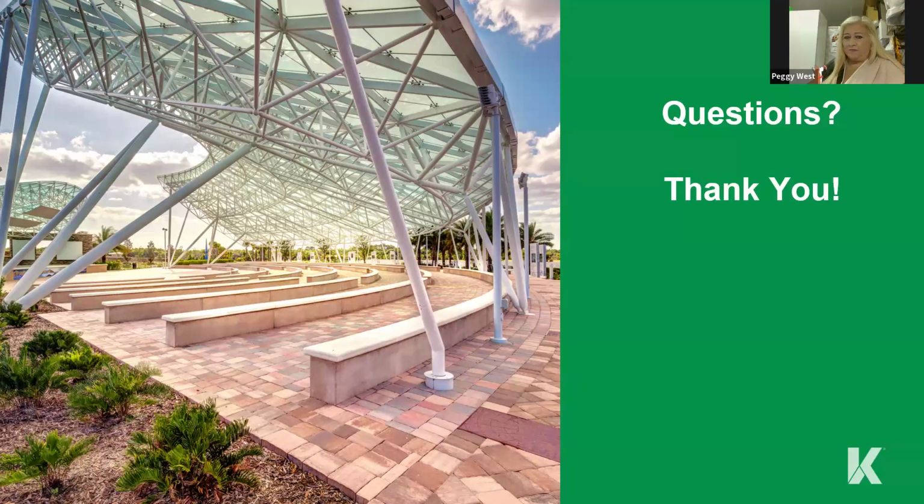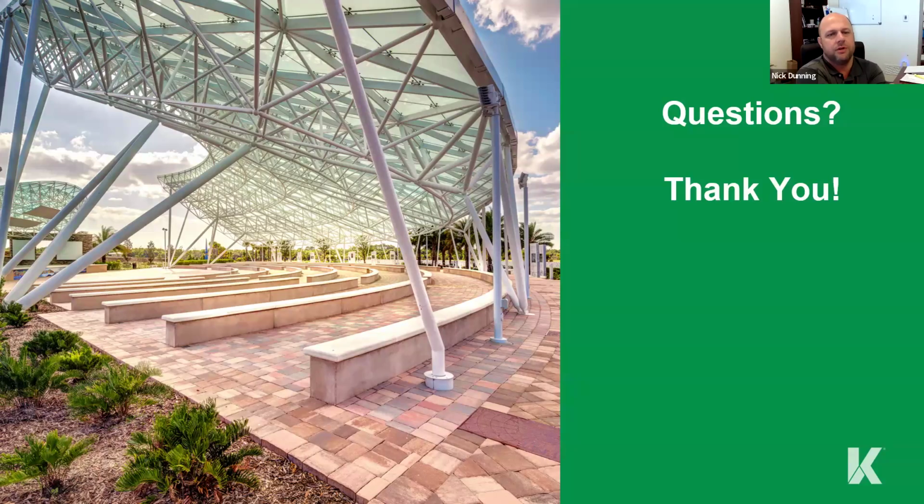One thing to keep in mind while we're waiting for questions: we talk about drainage planes, all these types of things in the wood frame. Say you have an exterior project where you're putting in Hardie board. Everyone likes the Hardie. It's going to hold up. It's a cementitious product. The issue we see is people do not understand that if they have, say, T1-11, which is a structural sheathing, and they take that off and put on Hardie, you have to make sure you put sheathing back. Things like Hardie are not structural in that aspect.